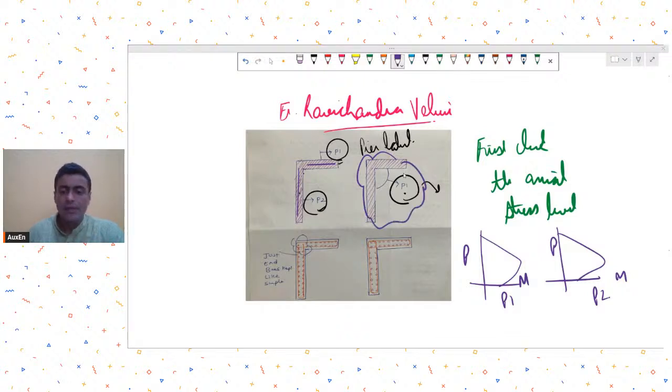If not, it is always better, because what is happening in ETABS software when you give one pier label to both the legs is that it will take combined section properties and find out a combined PM interaction curve.